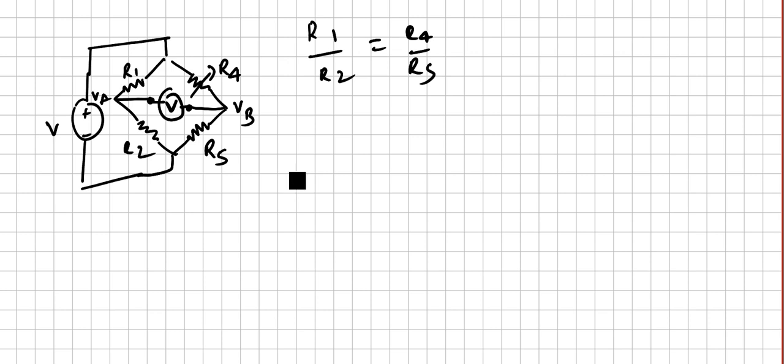Both R1 and R2 are fixed resistors of known and very precisely calculated value. R4 is a rheostat which has very precise movement, so we can measure the value of R4 very accurately. Now comes the value to be measured, which is Rs.